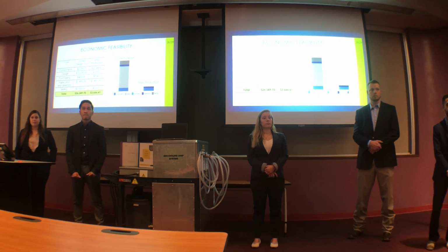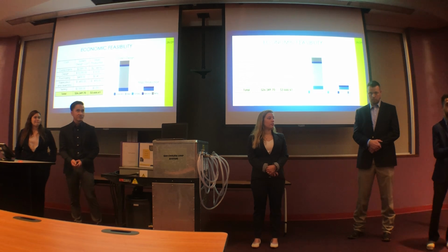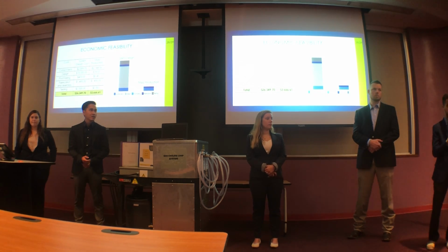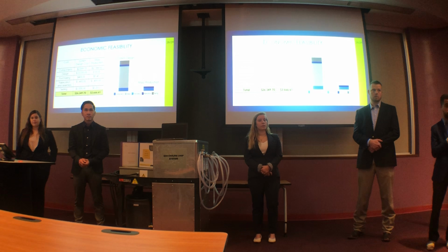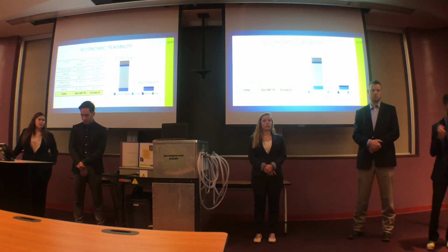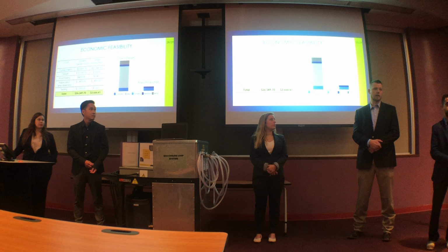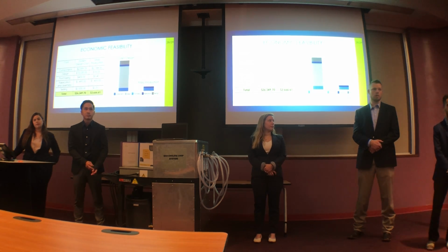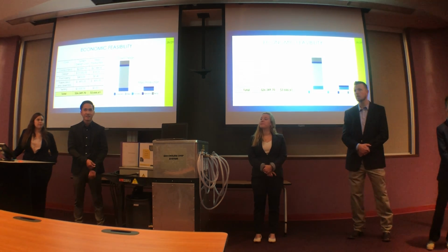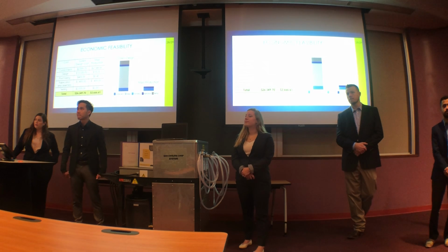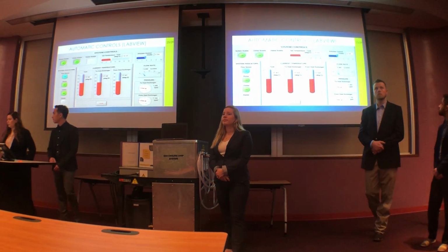So if it's safety, does it prevent an arc or something like that? No. I mean, then what's unsafe about it? So the contactor doesn't burn out. We tested it out before the 5 volts, and it will keep turning on, turning off. We're using it as a pilot relay. That way we don't pull as much current through the DAC. Okay. So there's no danger to the user? No. It's for the system. Safety for the system.